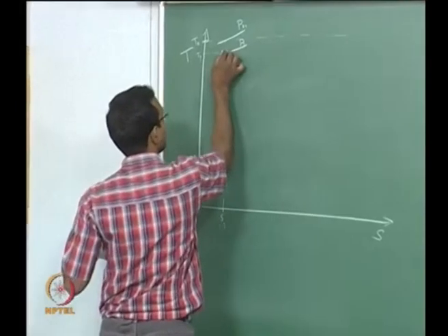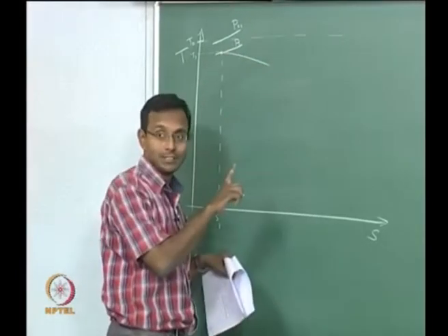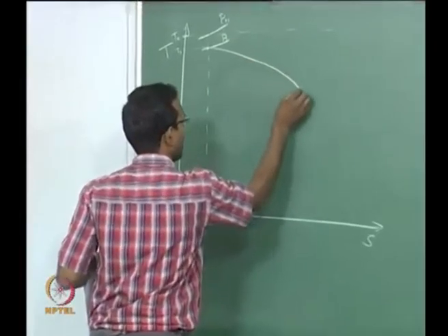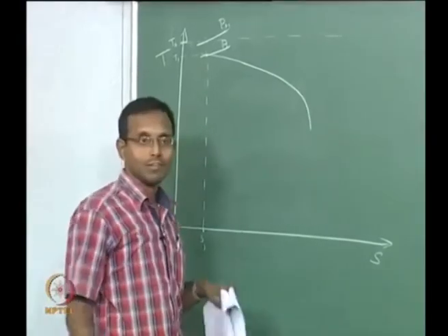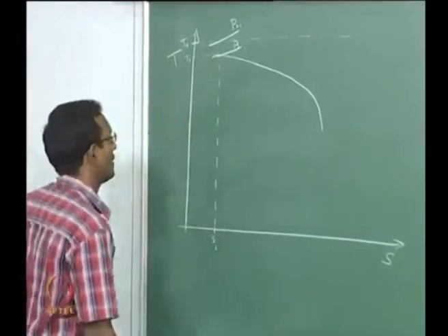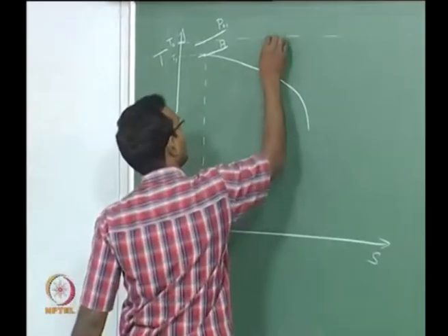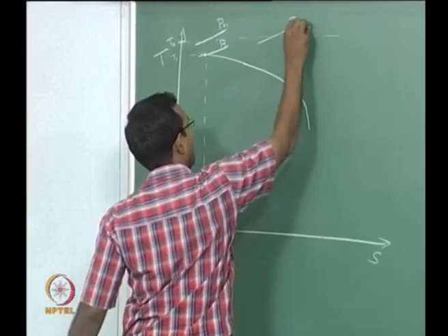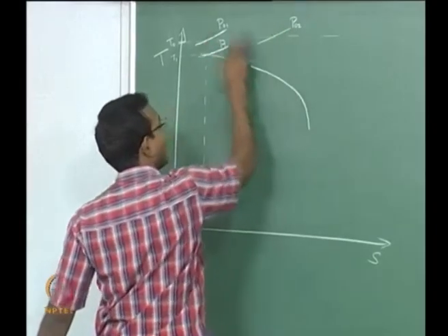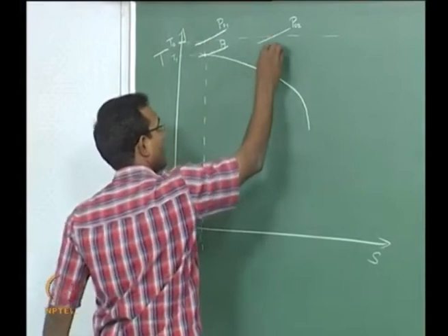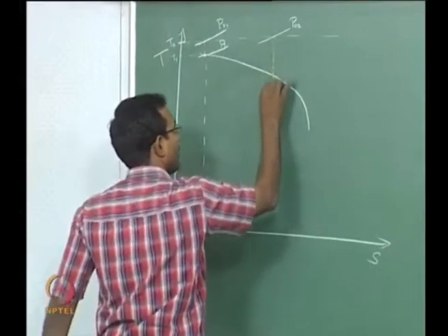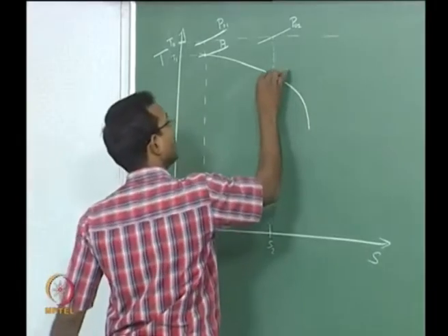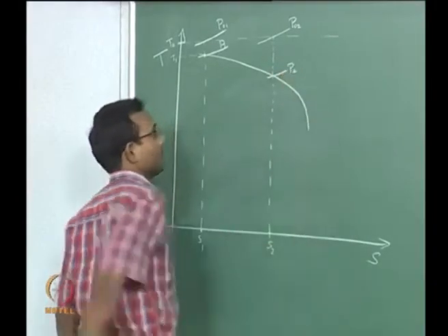So it is going to go something like this, and it will keep doing this till M equal to 1, and we know that the change is much higher when I go to M equal to 1. The curve does something like this. If I want to pick a point P2 in the middle, it would have gone to some other P02 here, basically P0 dropped by some amount. From P01 it came down to a lower curve P02, and then this will be my S2 and this will be my P2 curve.